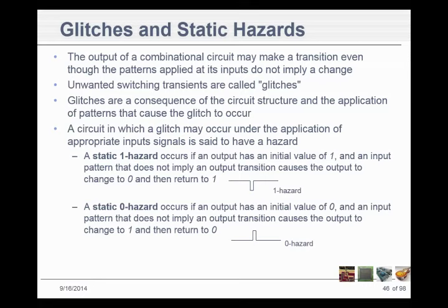We could set them up also to run and run and run and run, because sometimes we would run until we hit a certain instruction. Sometimes we would run until we saw certain data on the data bus. Sometimes we would have it run and keep running until it saw a glitch, because we weren't finding anything anywhere else. So let's see if there's a glitch.